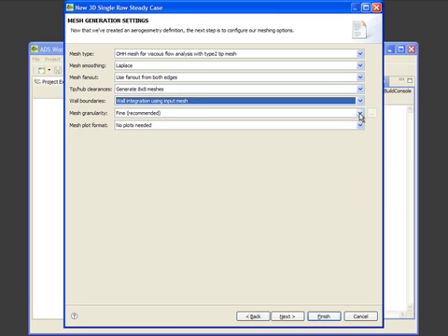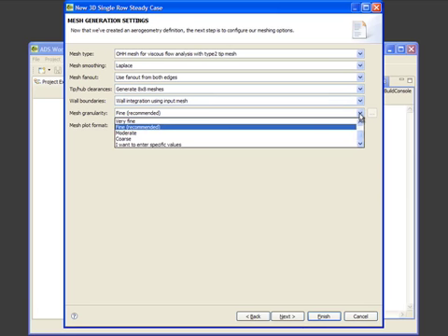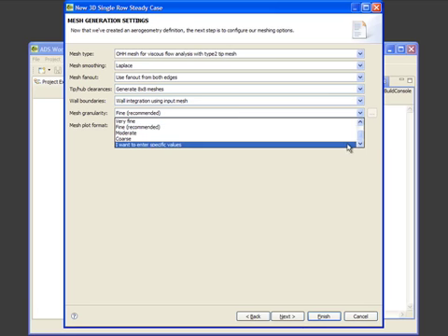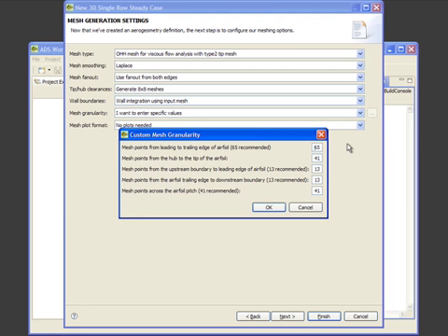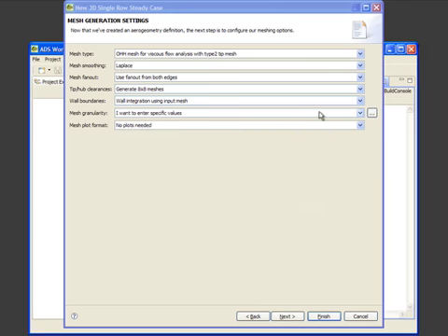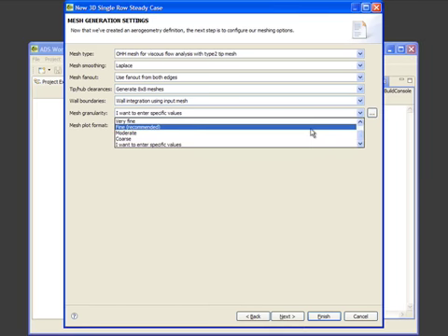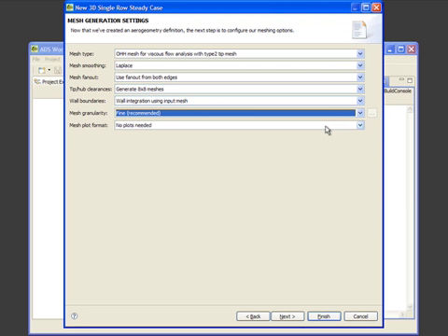For the mesh granularity, we also have many options for you. Some are already preset. However, if you feel you need to be more specific, you have the ability to add in your own values. However, what we recommend is fine. This is a combination of speed and accuracy that we find is very useful.